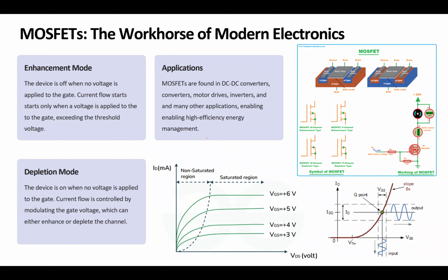Okay, then you cannot go higher than that for the current. So the current gets saturated, but if you add more voltage to the gate, it causes the voltage over the MOSFET to get increased. It wouldn't allow more current, but it just allows more voltage.